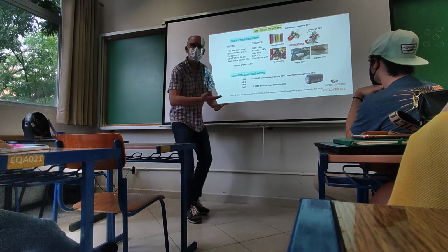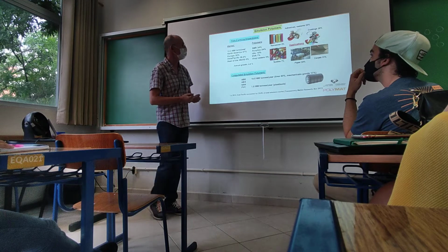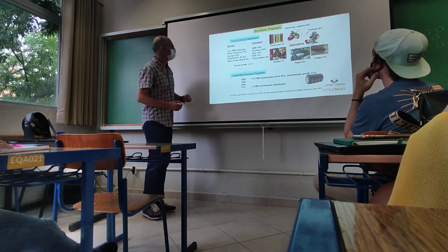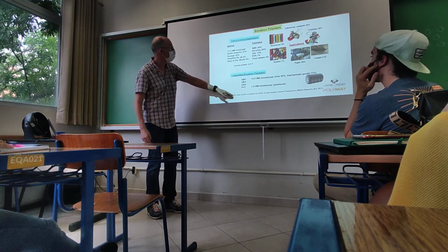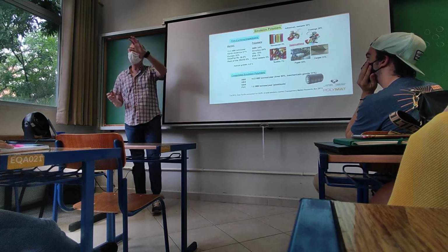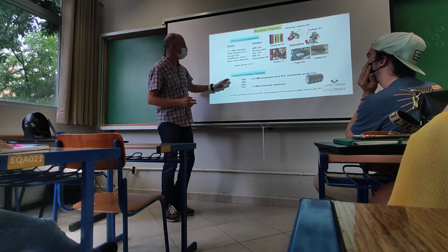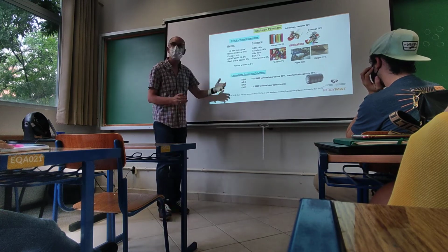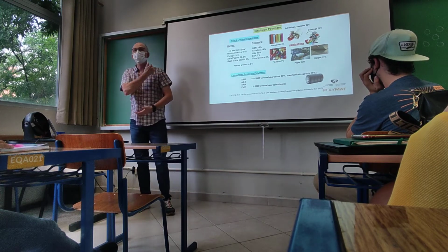Carpet backing. The carpets, in the back they have styrene butadiene, carboxylated styrene butadiene latex. Textiles also have it, or non-woven also. Okay? So you see how this is distributed. These are numbers from 2012, but they haven't changed much. The total production of latex is at around 14 million tons in the world. So, in the coagulated fashion, SBR, ABS, styrene acrylonitrile, and PVC. PVC is produced by emulsion polymerization to produce plastisols, and also for jackets.